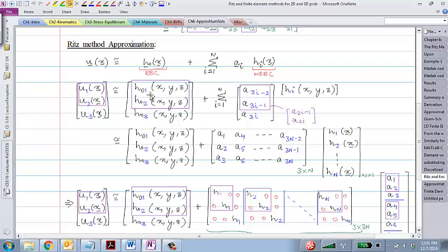And you can imagine, so for example, if I have a cantilever beam like this, I say that I'll apply an end load at the tip, and I'm saying that the fixed end here isn't really fixed, but maybe it slides down by some amount. So H0 in the vertical direction would be, let's say, 1 inch. Okay. H0 in the horizontal direction would be 0. H0 in the out of plane direction would be 0. So that's what these three components mean.